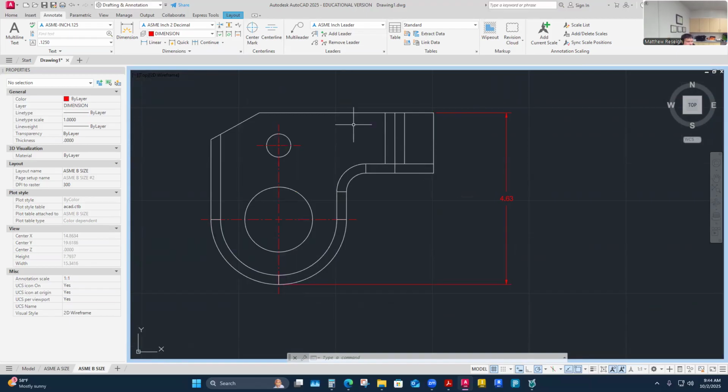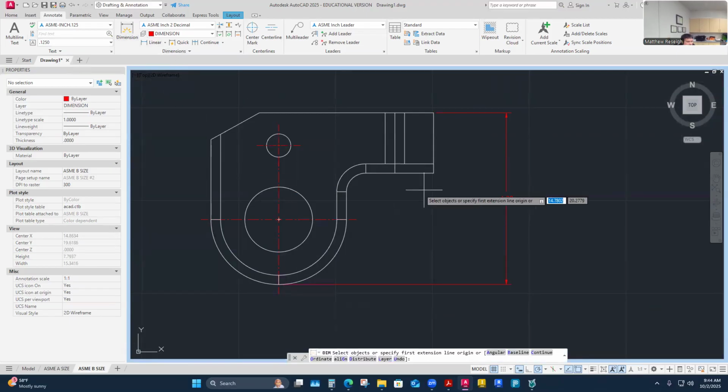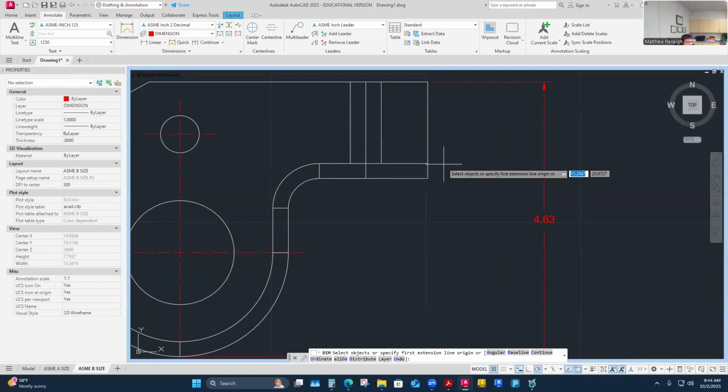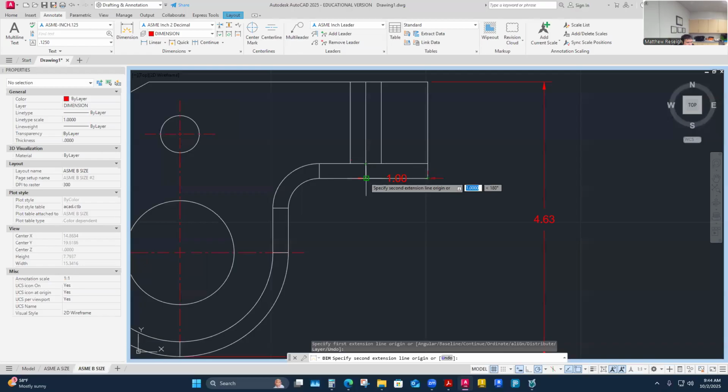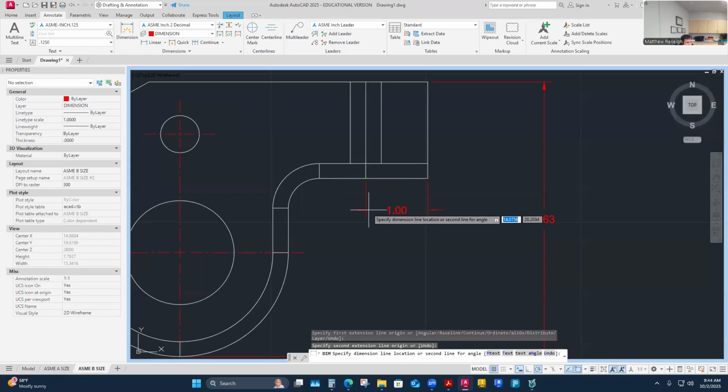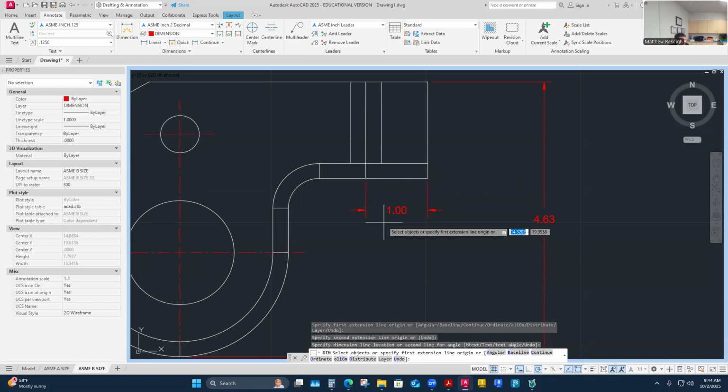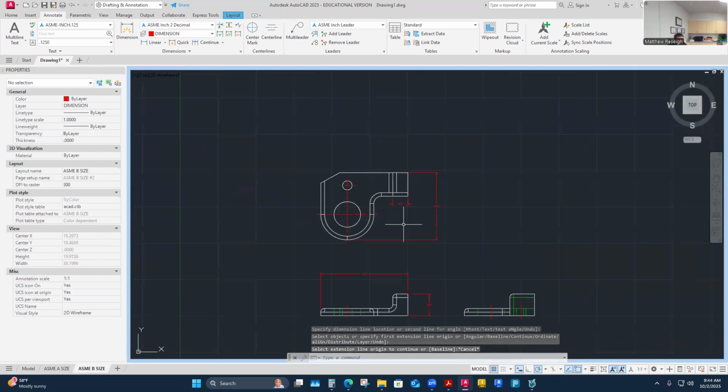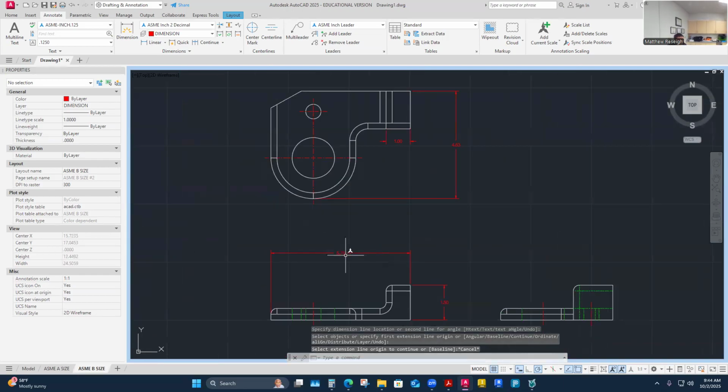This is the width, and I need to know which visible line I need to dimension to, but I'm not going to dimension to the fillet. I'm going to dimension to the actual width, which should be kind of from here to essentially here, right? It's like 1 inch in width here in that view. And I like pulling it from here because that's a datum right here. I've established potentially this one as this datum point, and I've actually pulled that from considering this edge, 1 inch. That's a size of the foot, kind of. There's a little bit more size to it.